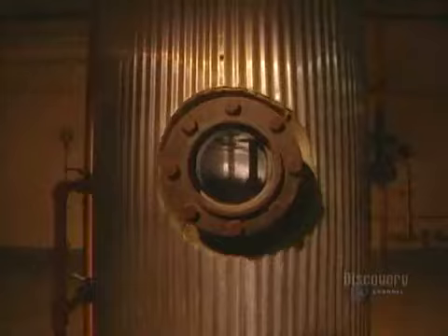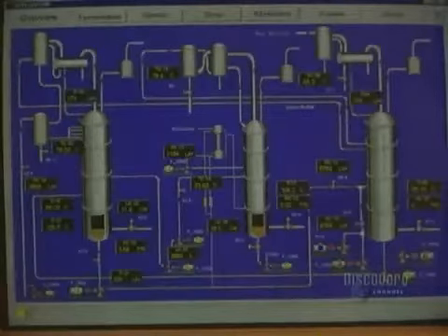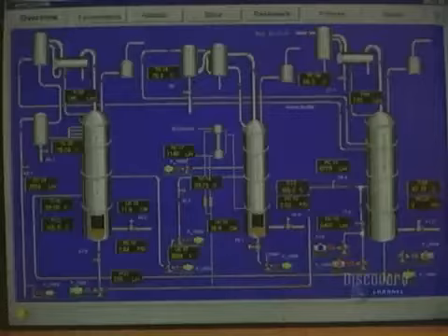The fermented mash has a 13% alcohol content. They now move on to the next step, distillation, which condenses the vapors of the mix. It's in this 3-column distillation system at a temperature of 85.5 degrees that the mash ferments and is distilled by live steam to separate the alcohol. All the distillation columns are continually monitored.